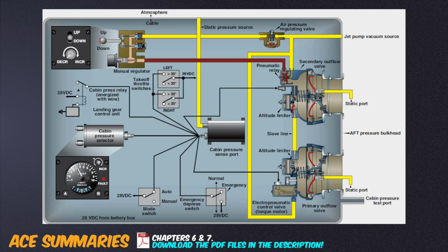Cabin pressure is measured as a differential between the pressure outside the aircraft and within the cabin. It can be thought of as a PSI value of the internal air mass pushing outwards on the fuselage, for example, 8.21 psi. Cabin pressurization is controlled by the outflow valve. It restricts outflow if the cabin pressure needs to be increased, and it liberates outflow if the cabin pressure needs